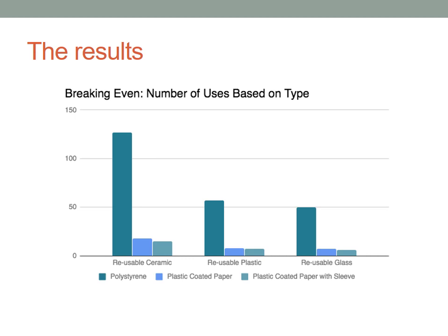So reusable plastic is, again, one of the most popular types of reusable cups. But when we choose reusable plastics, we have to be careful about what we're choosing in terms of polymers and its end of life. So I told you before that PLA is not actually a good plastic to use for these type of cups. One of the reasons it's not good is because it has a relatively low hardness rating, i.e. it's a soft plastic. And also it's quite malleable at relatively low temperatures.